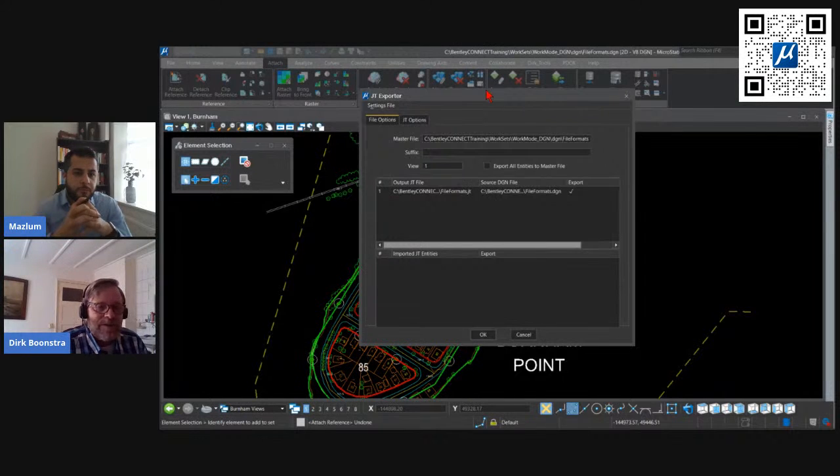It's like translating again. And in every translation, you can lose information. So in your workflow, you should always try to avoid making these kinds of conversions. Always try to use the original format, especially if you don't need to make changes to it. And then you can just keep it and use it as a reference. Minimize the conversions, because you always lose information. You never gain information by converting.